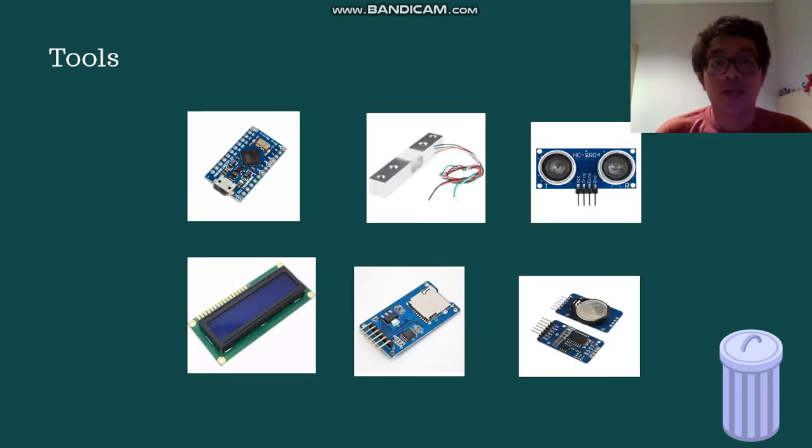So these are the main tools to do it. Aside from cables and PCB, the brain I use is the Arduino Pro Micro. Why? Because it is small, it is cheap, and it is enough for the system to run reliably. And then the second one is the load sensor, and then the ultrasonic sensors, LCD display, SD card module, and real-time clock module.